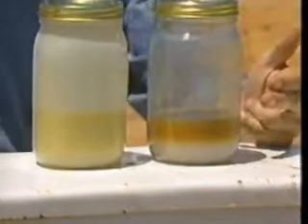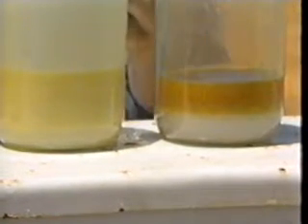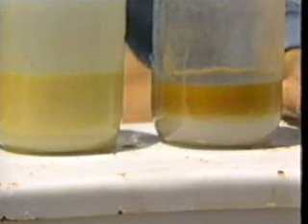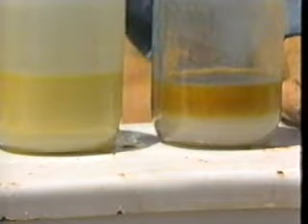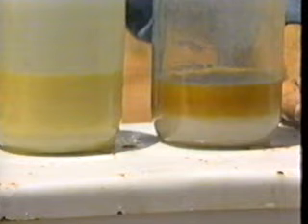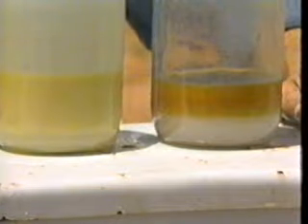As you can see, there is a difference. In just a few seconds, the heated emulsion has separated more than the unheated emulsion. But heat must be applied only as necessary. Too much heat will waste energy and cause greater wear on the equipment. Also, excessive heat can burn off the valuable lighter ends of crude oil, changing the oil's gravity and resulting in lost revenue.